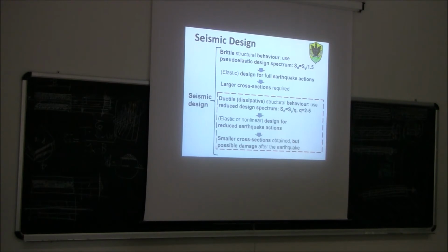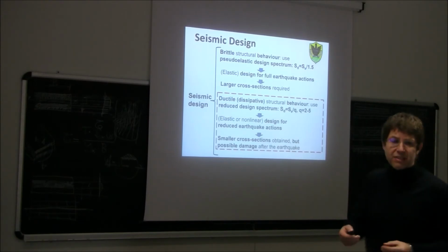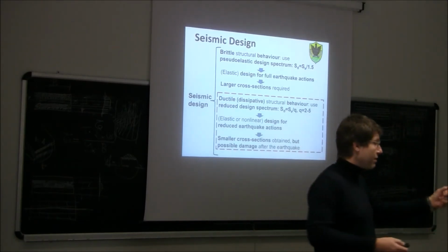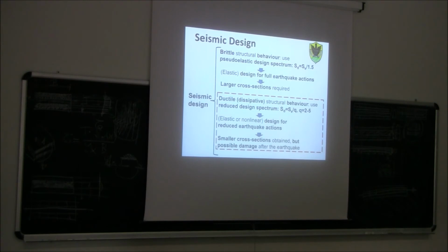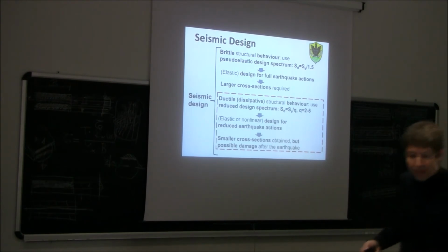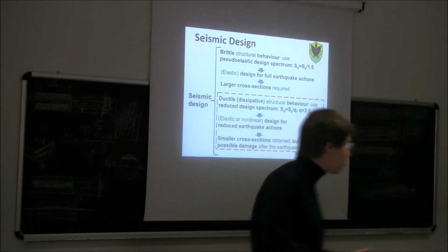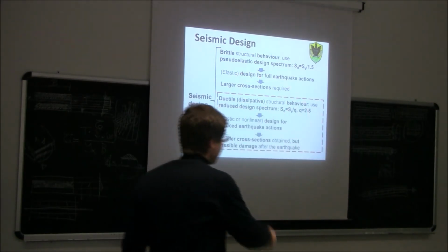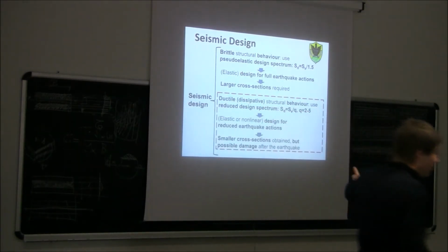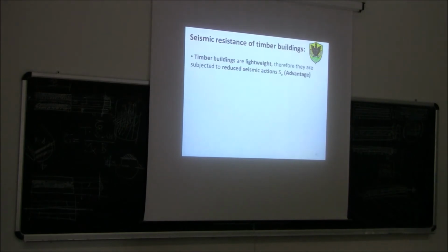So the idea would be, if I can make sure that I have, rather than plasticization of rebars, plasticization of fasteners, this plasticization of fasteners may in some way replace the plasticization of the rebar that I don't have, and I can get some energy dissipation, so I can also have a plastic design there, and so use a Q factor.